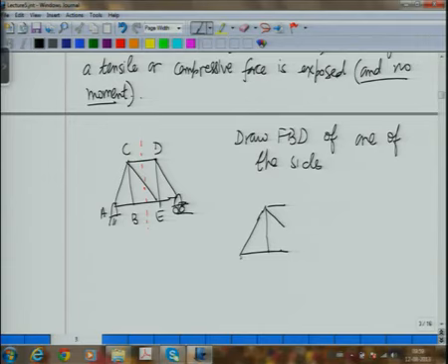Now, at point A, I will show A sub y is equal to 1000 newtons, A sub x was 0. Now, within this, I have to show all the external forces. Now, point B is also within this left part. On point B, 1000 Newton force is acting, so I have to show this.